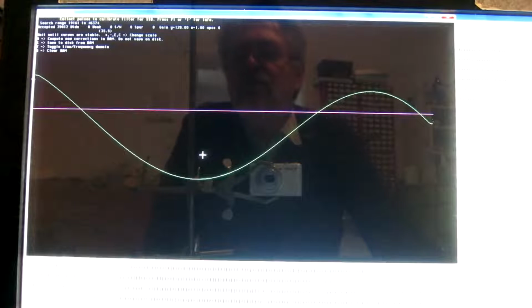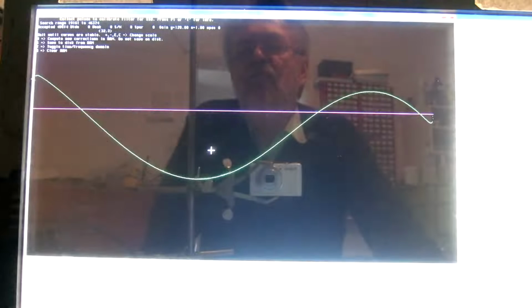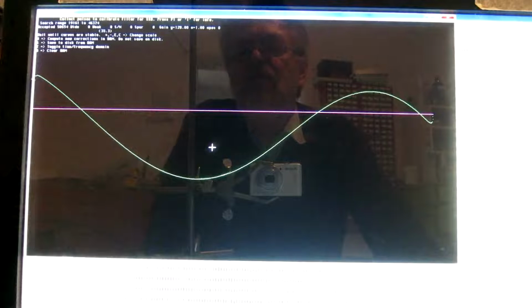The reason for this is that Linrad takes the pulses one by one and cuts away what is at some distance away from the pulse. And that is the same as a high-pass filter. It means the DC component is removed. And for that reason there is a discontinuity here at the center.